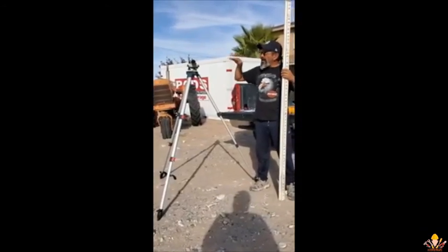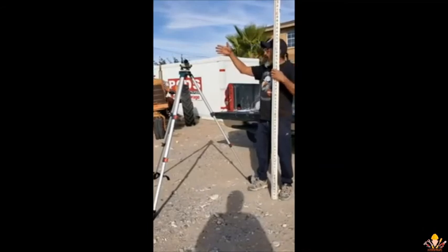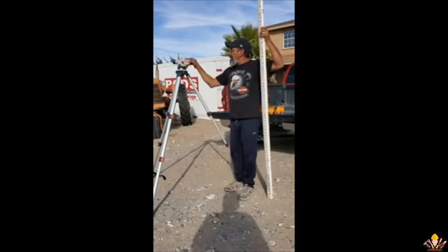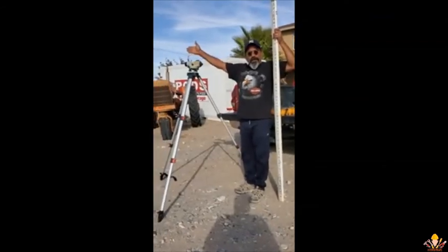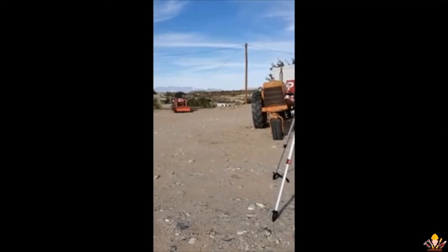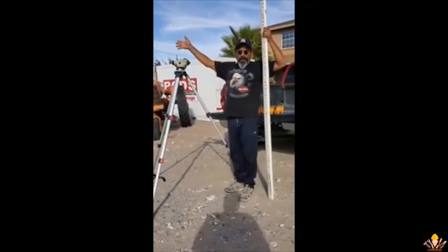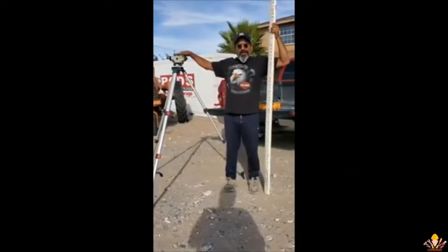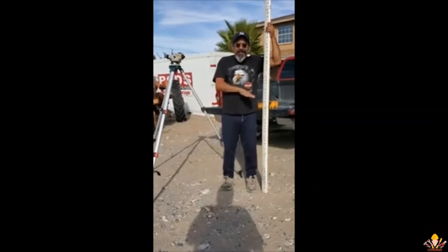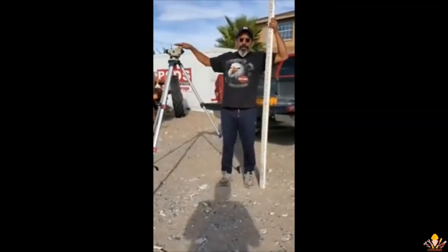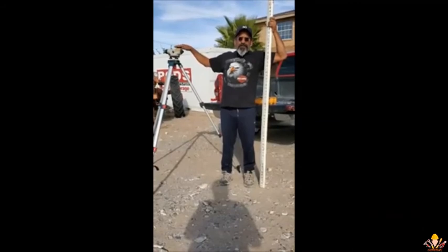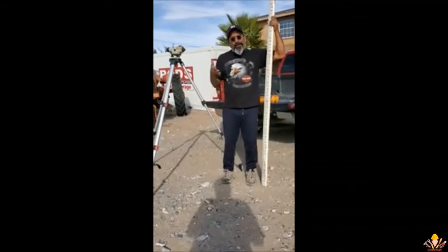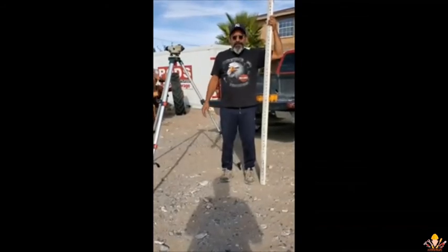Now let's say we're going to measure a building that would be on the other side. You would turn this to the side. You would shoot where the grade rod would be at your building or your other grade stick, and that would be what your measurement is minus the actual height of your transit level, and it will give you your actual reading. And then from there you can determine whether you need to dig down, make a fill, or make a cut, or leave it as it is.